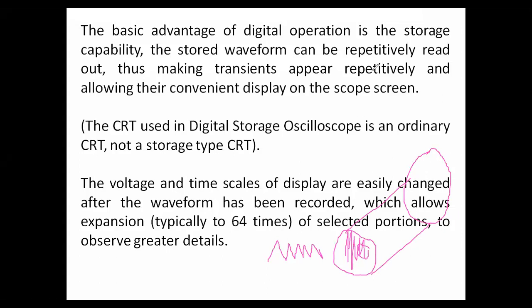That is one of the major benefits of using a digital storage oscilloscope, because the signals are stored in the memory, so at any time we can retrieve them. Suppose this situation happened during the night duty, and you come in the morning and have to observe that information. What happened in the night, we can easily display and analyze. Like this we have more benefits using the digital storage oscilloscope.